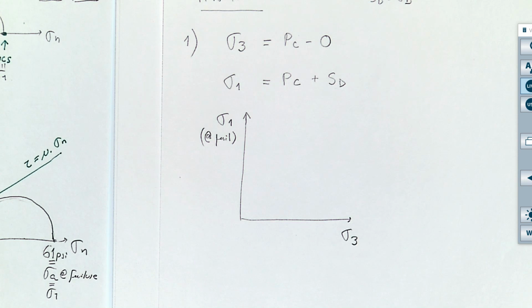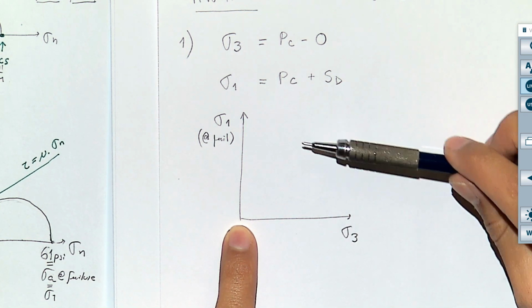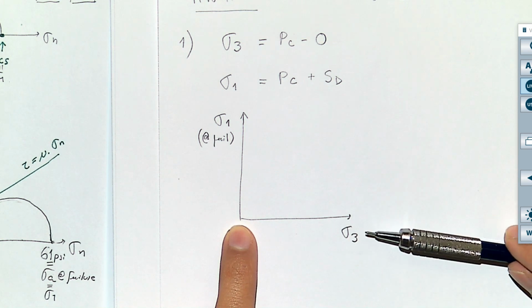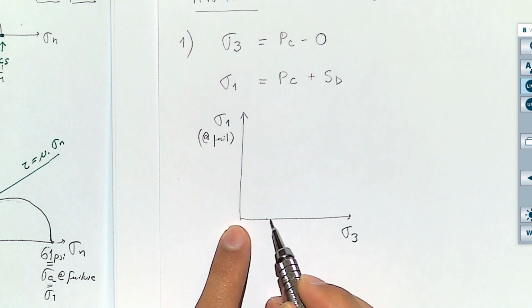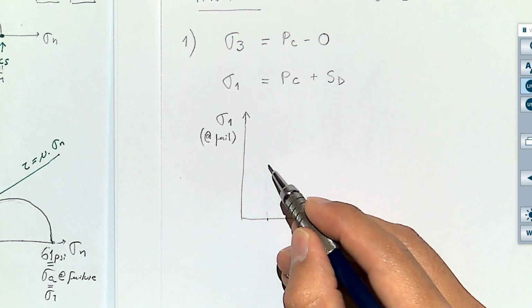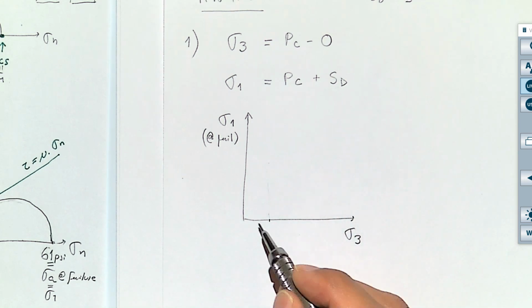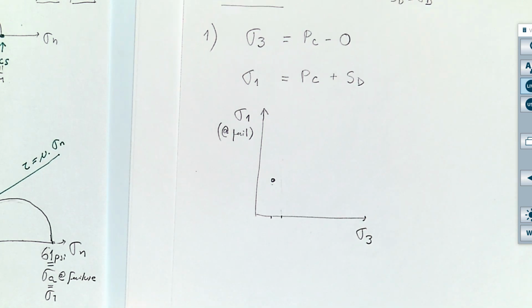Do you remember, for a typical friction angle of 30 degrees and an uncemented material, what was the maximum stress that you can apply in one direction, given that your confining stress is some value, or what we call stress anisotropy? I told you the number you have to remember: 3 times, right? So if I had this effective stress, the material will likely resist a value, let me start here, somewhere over there, and that's going to be a point.